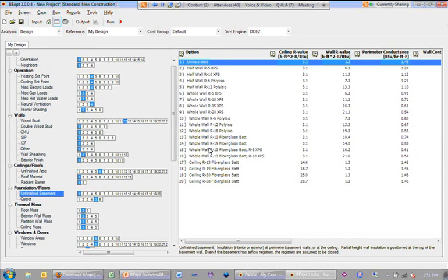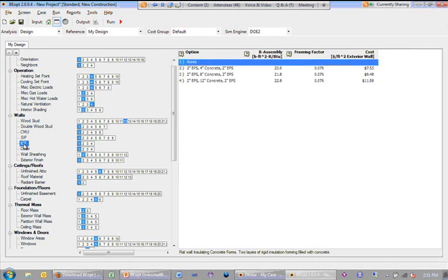Thanks. People that sell insulated concrete form houses talk about a thermal effect or a thermal inertia effect of the mass of the walls. And I have used BOPT and looked at that and not seen much of an effect. And I just wanted to be assured that in order to get that right, it would need to be doing hour-by-hour calculations. But does BOPT always do hour-by-hour, whether you're using DOE or Energy Plus or all those options?